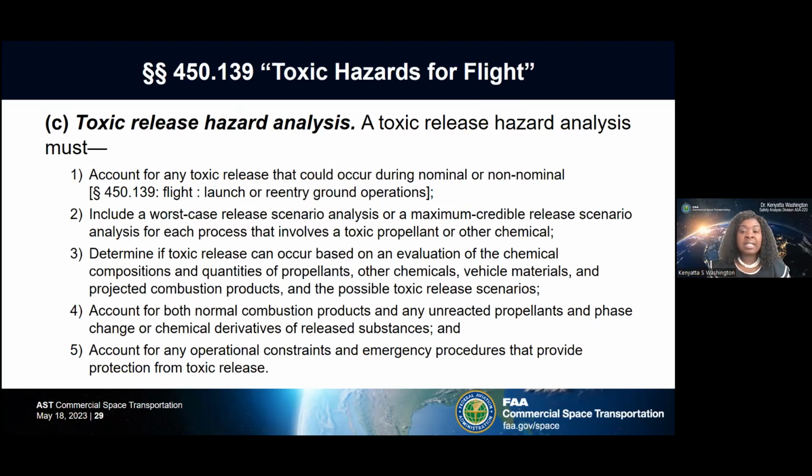A toxic release hazard analysis should account for any data needed to determine if the public is protected from any possible toxic release that could occur during a nominal or non-nominal flight, launch, or reentry ground operations. The analysis must include a worst-case release scenario analysis or maximum credible release scenario for each process that involves a toxic propellant or chemical.